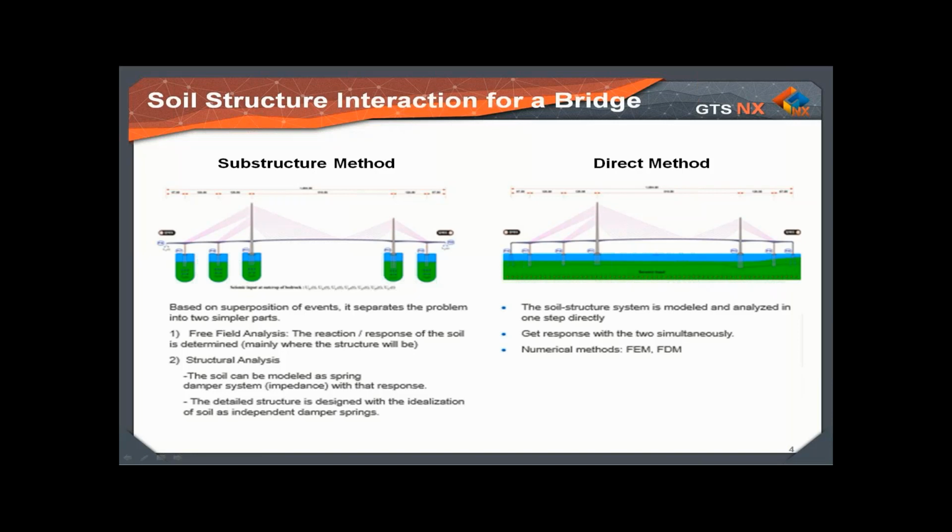The method proceeds as follows. First, calculate the free field response of the site without any embedding of the structure, and analyze the soil deposit as a dynamic subsystem. This response will be obtained at the nodes where the structure will be inserted subsequently, determining the force displacement relationship.